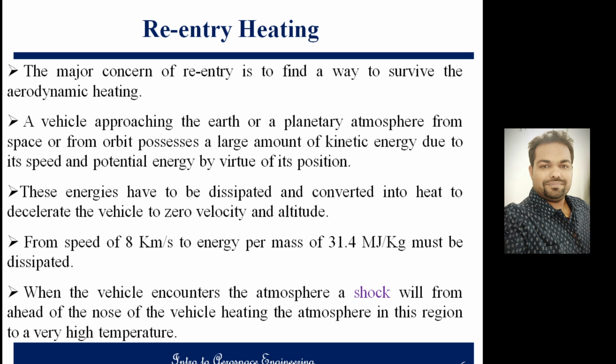In this manner, the vehicle's kinetic energy is converted into heat. If all the vehicle's kinetic energy were converted into heat within the vehicle itself, it would be more than enough to vaporize the vehicle. That condition should not exist. That's why I said that aerodynamic heating is a big challenge and we need to avoid it. We need to minimize it. Otherwise, it is very difficult to enter into the Earth atmosphere.